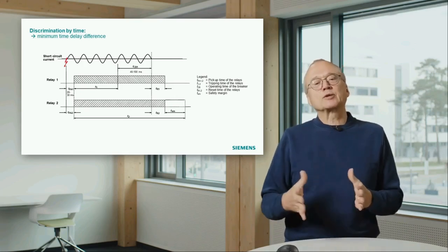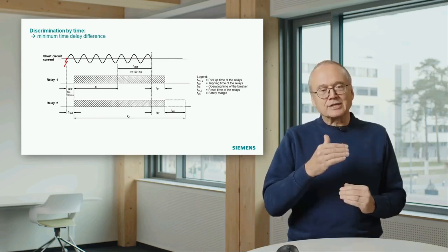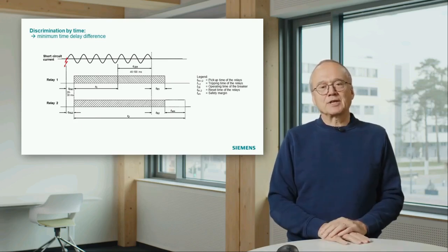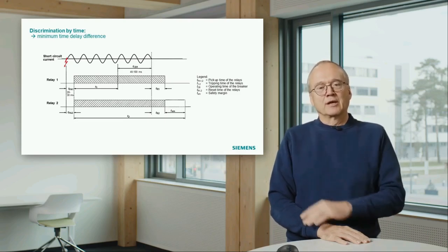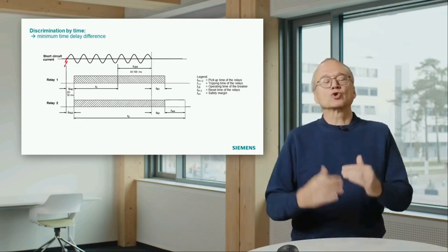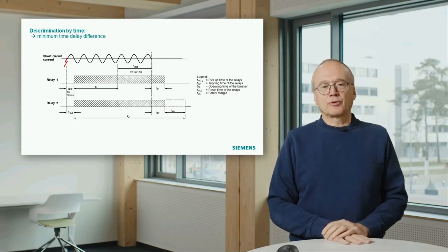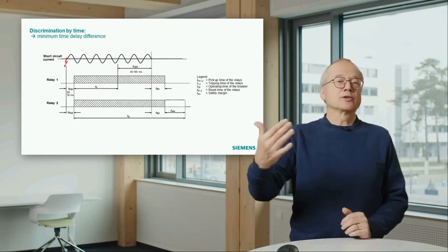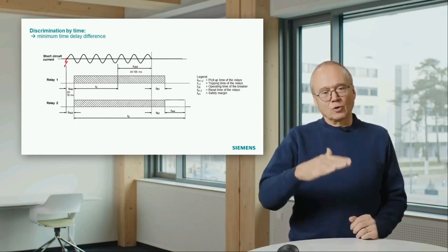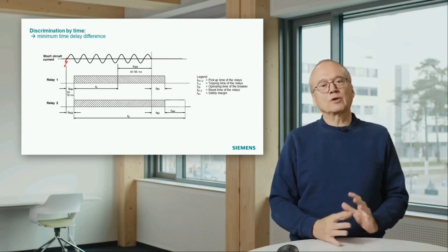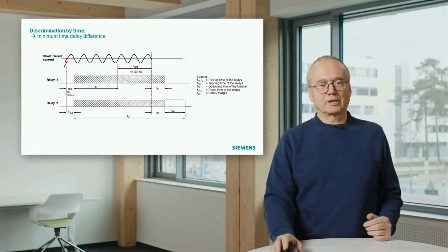And with this calculation you end up in required differences of the timer setting in the range of 200, 250, 300 milliseconds. You should not go below that. In my example I took 300 milliseconds. It's more the upper end. I think nowadays you can also go down to 250 or even to 200, but you must be pretty much careful then.